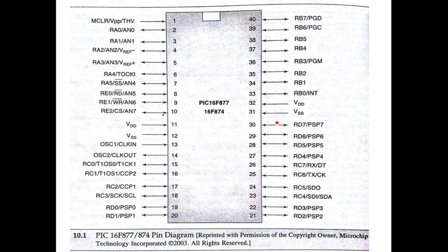Okay, 4 pins for power supply, 2 pins for connecting the crystal. You can see here, pin number 13 and 14 are for connecting the crystal, and one is the master clear pin that can be seen somewhere. This is the master clear pin, pin number 1.